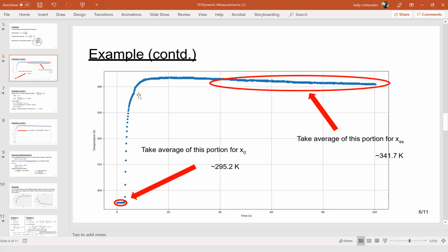So here's the data if we plotted it. I think this is the thermistor data. And you can kind of see it looks really close to what we showed, like the perfect example with the thermometer. Here's a little overshoot right here. See, here's our steady state value over here, and it kind of has a little hump before that. So it's got a little overshoot. There might be a little bit of creep type stuff here. You know, it's kind of decreasing slowly. What's causing that? I don't know. But there's more or less the steady state region here where it's not really changing. The temperature measurement is not really changing that much. And over here, you've got a few points of an initial state, you know, this little flat line down here.